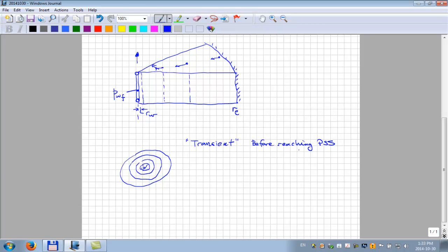And what they would do is that they would usually produce a well, and then they would study how the bottom hole flowing pressure for a constant rate changed as a function of time during that period. So that's a field of engineering. And we don't really call this pseudo-steady state anymore. This is old school. It's now called boundary dominated.